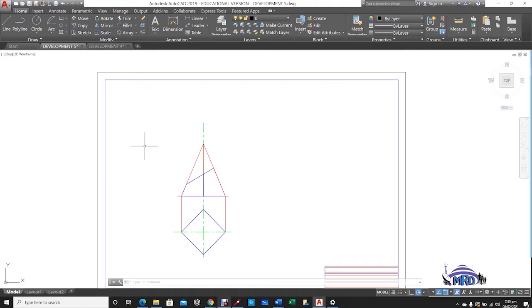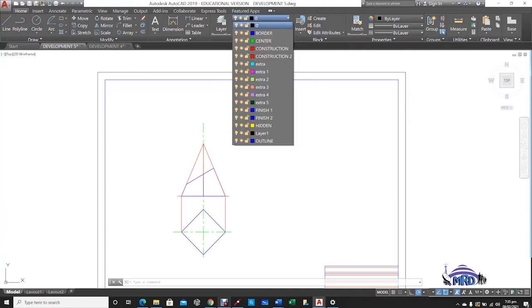But here, you're given this shape and you're asked to produce the development. Before we can get to the development, however, we have to look at what the complete plan would look like. And along the way for producing the plan, we'll also have to produce an elevation. So it's regular orthographic projection. Let's see how we can proceed. I'll be dropping in some lines using different colors. We know that these lines would still be construction lines, but I'm just dropping them in different colors for clarity.